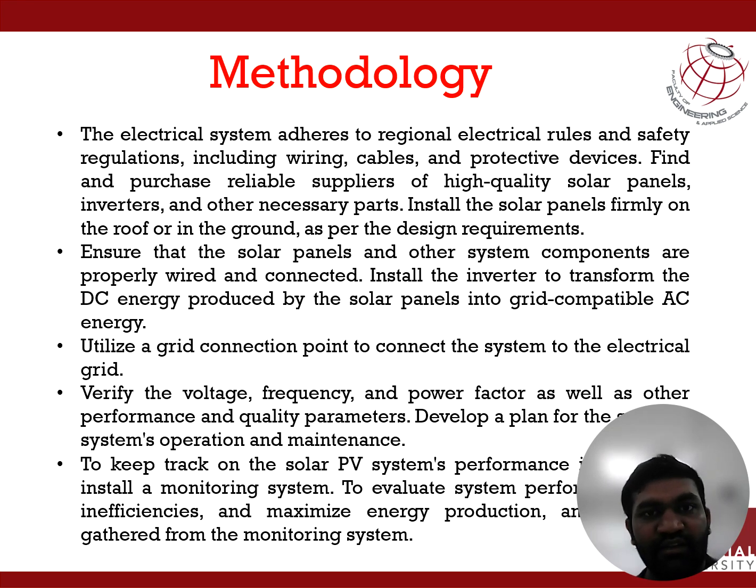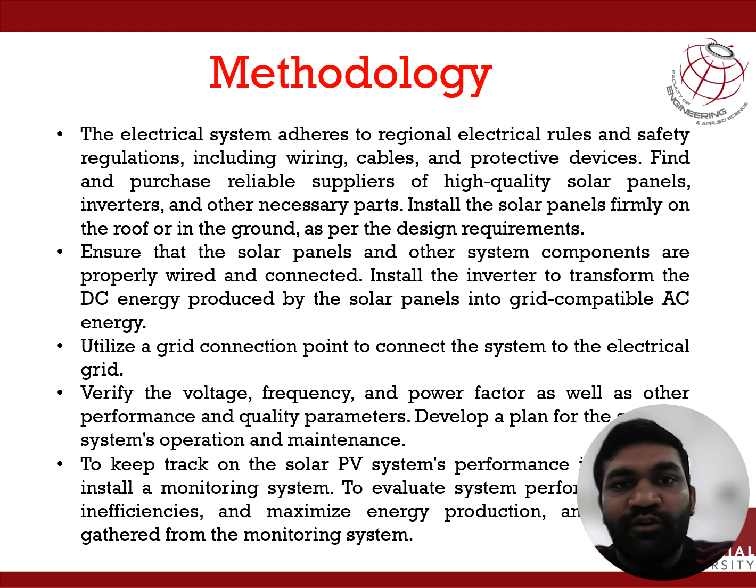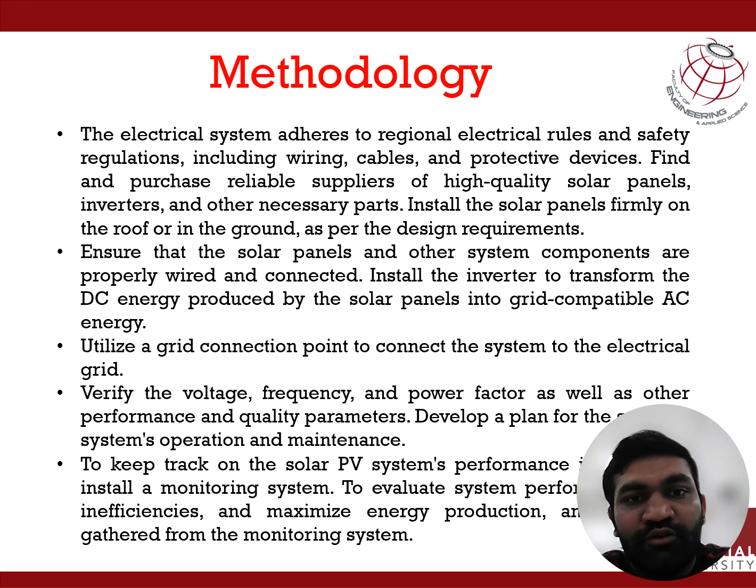Next, the electrical system adheres to regional electrical rules and safety regulations, including wiring, cables, and protective devices. Find and purchase reliable supplies of high quality solar panels, inverters, and other necessary parts. For the installation, mount the solar panels firmly on the roof or the ground as per the design requirements. So basically, we are following this methodology when designing our project. Ensure that the solar panels and the other system components are properly wired and connected, so we can get a proper output.